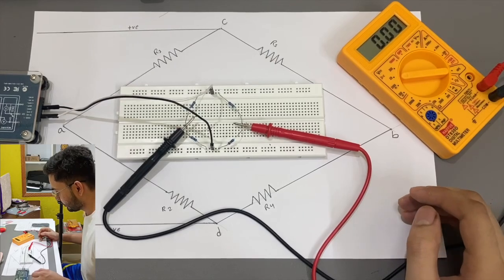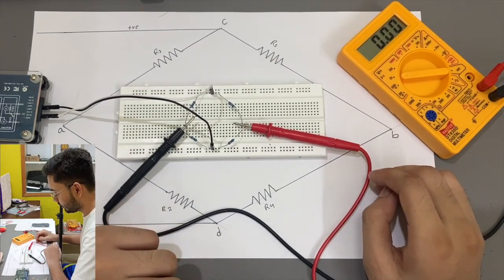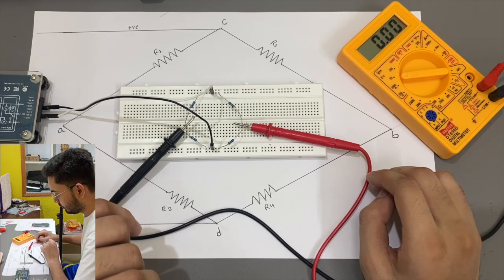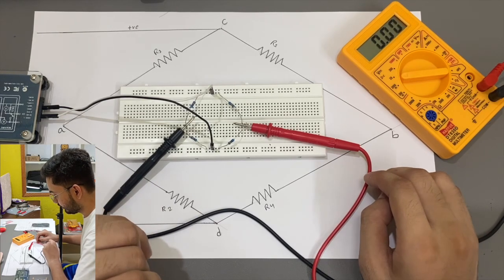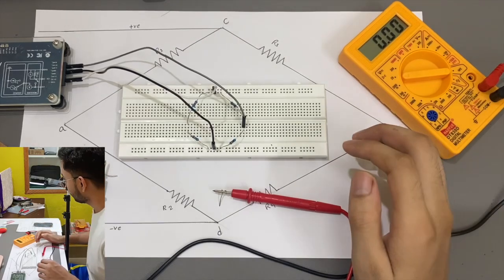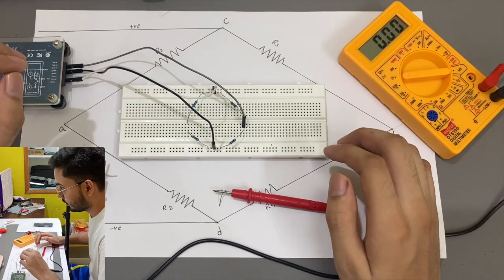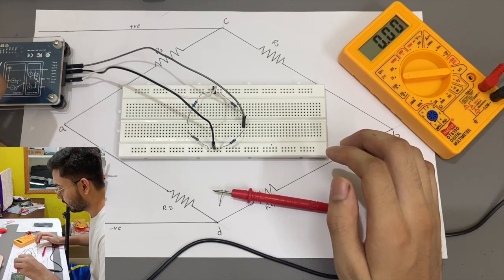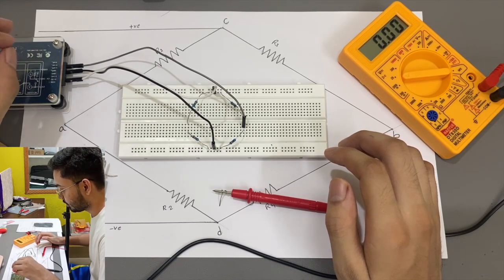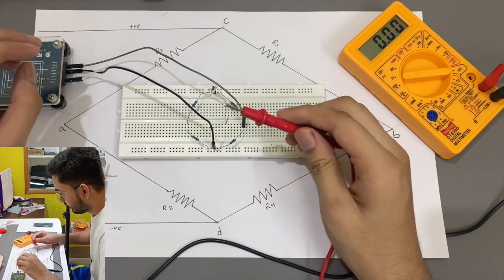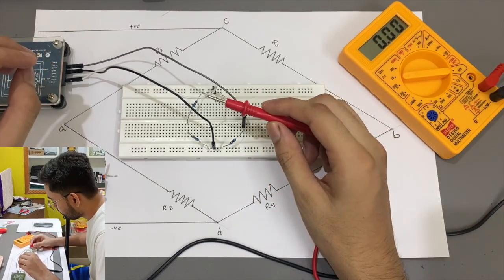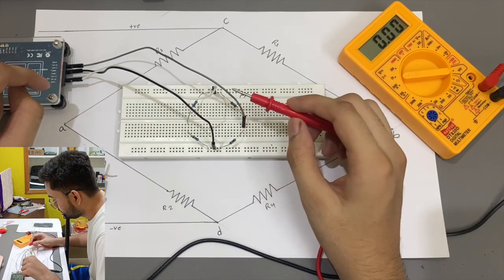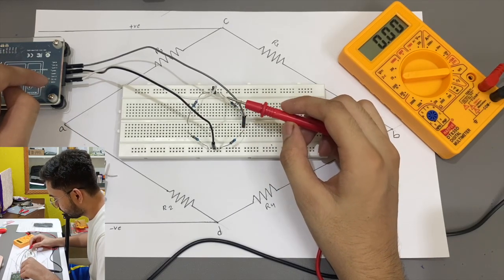Now we will repeat the same, but we change the input voltage from 2.5 volt to 2.5 plus sin omega t. We will change this value using PixelPulse 2 software. Now this is my circuit in which I provide an input voltage of 2.5 plus 1 sin omega t instead of 2.5 volt. We will provide this input voltage through PixelPulse. Let's see the wire connection. White one is connected from channel A, black from ground and grey from channel B.